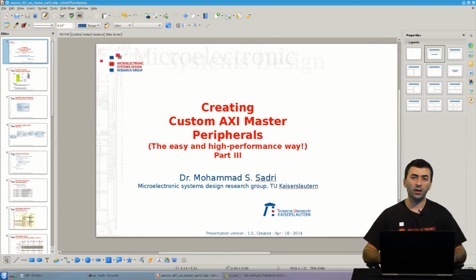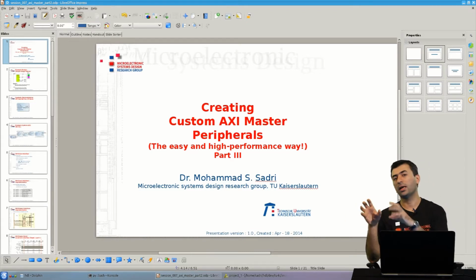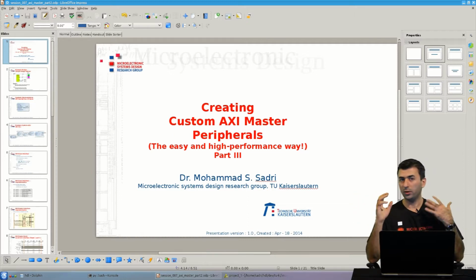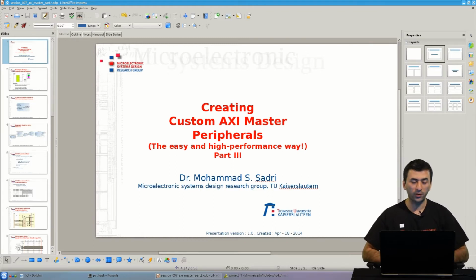This simulation is extremely important because it allows you to find the problems with your design before you go into real hardware. So if you have a piece of IP block or something that you need to interface to, and that piece of IP does not have any functional model, it's always a good idea to create a functional model yourself to at least have a small amount of simulation that usually helps to find a large number of bugs in your design.